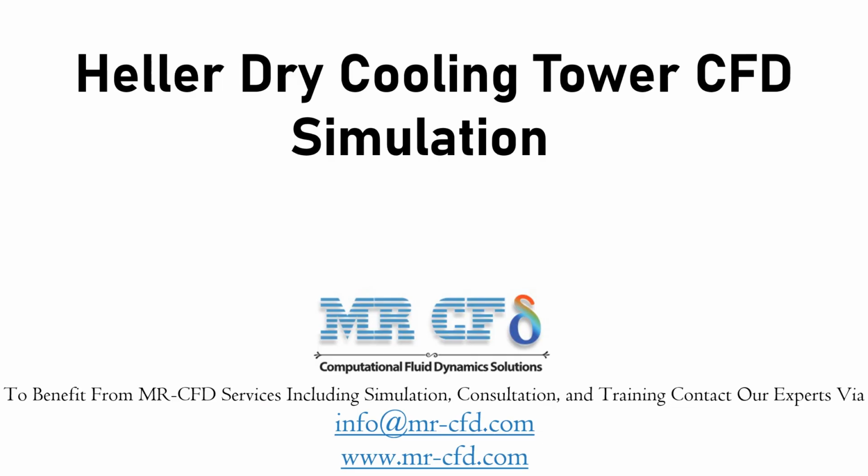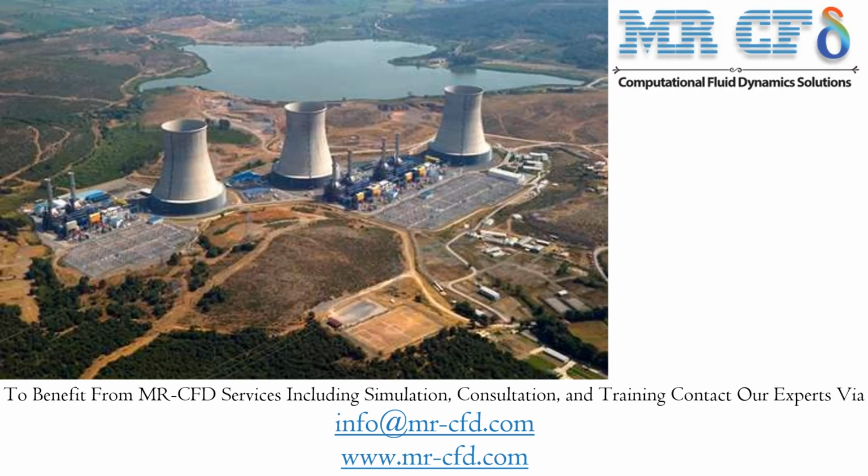In this project, we will simulate a Heller dry cooling tower. A dry cooling tower is used as a means of indirect heat transfer between the working fluid and the coolant. In a thermal plant, the working fluid exits the condenser and then is pumped into a ring of heat exchangers. These heat exchangers are air-cooled, which means that they are cooled by natural air suction caused by a temperature difference between the inside and the outside of the cooling tower. The greater the temperature difference between outside air and working fluid, the stronger the temperature driving force.